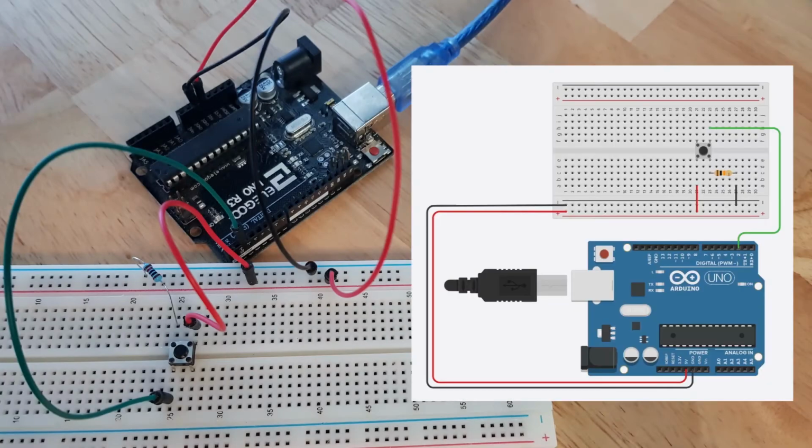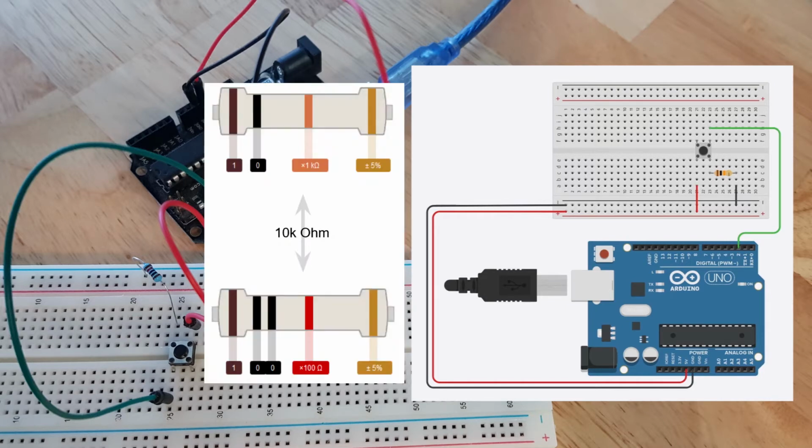So to measure the pulse, first we're going to create a small circuit with just a push button, and I have added a pull-down resistor to the push button, so the signal will be low by default, and when we press on the push button, the signal will go to high, so we can use the pulseIn function with the high mode. So on the circuit you can see we have one leg of the push button which is connected to a ground via a 10 kilo ohm resistor.